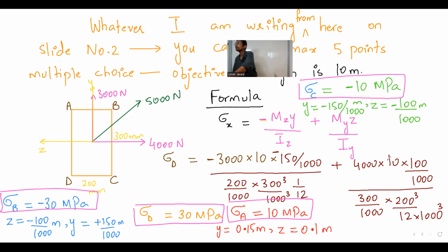I am applying force. This is a cantilever beam, right? I am applying the load at the end. The maximum moment will happen at the support. So the maximum bending stress will happen at the support. So if the maximum stress happens at the support and you have a cantilever beam, our professors used to tell us that the load is acting at the tip. This multiplied by length will be the supporting moment. I am skipping the statics part for you guys. I think you understand those things. 10 meter is the length of the beam.